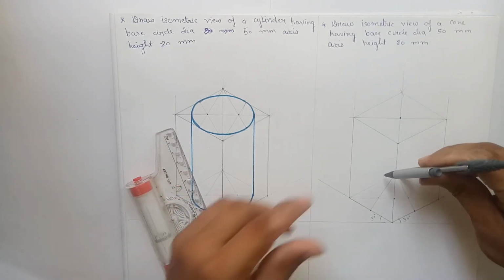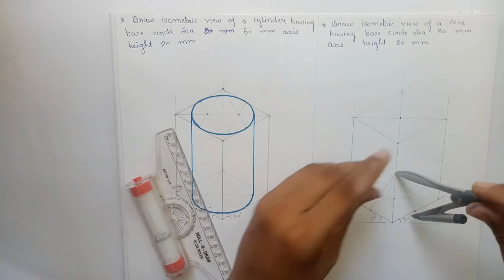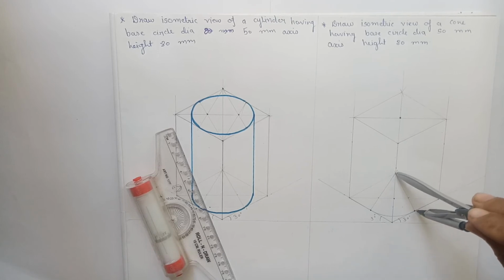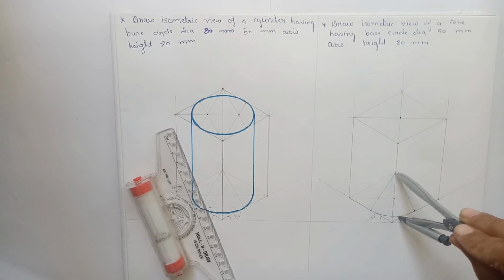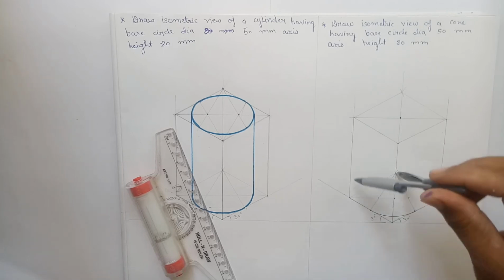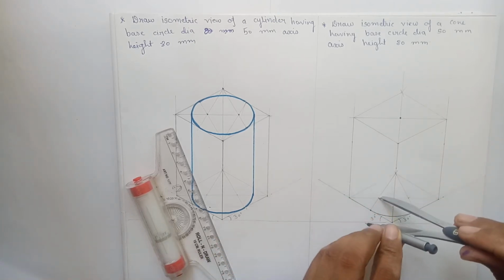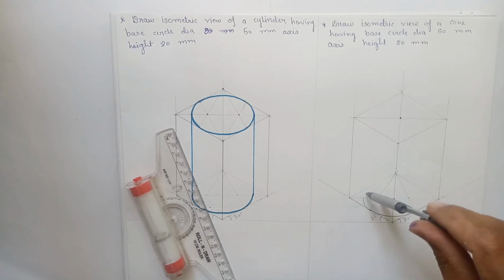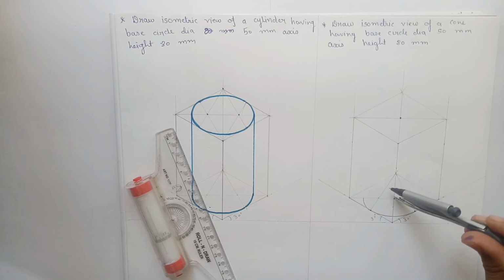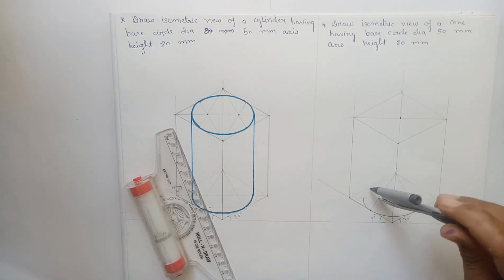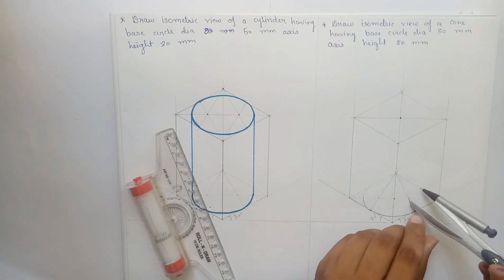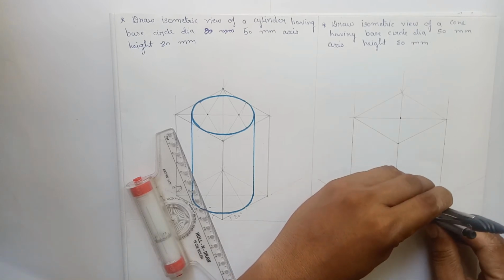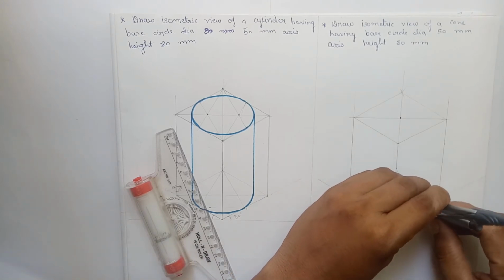First of all, put your hand over here, measure the midpoint, give an arc. Put your hand over here, measure the midpoint, give an arc. Now you can complete the circle like this, but the back part of the circle is not going to be visible. But draw the complete arc to understand the further method.